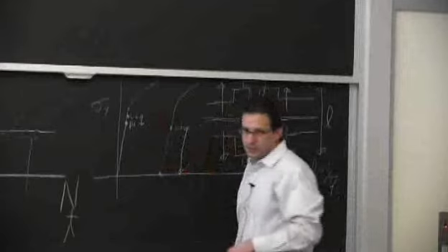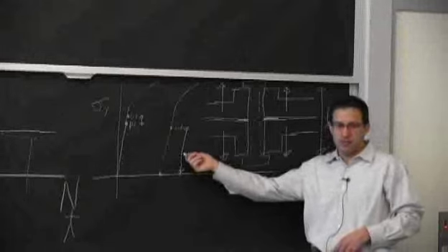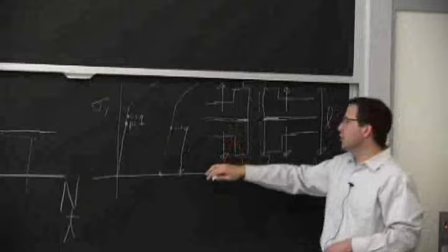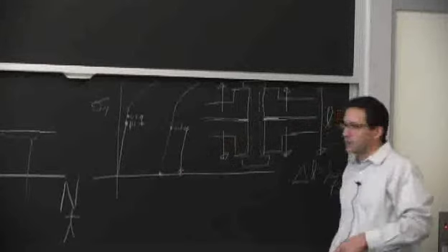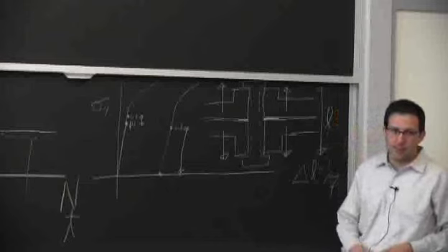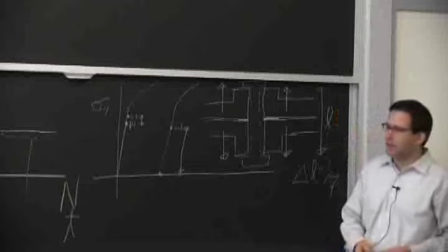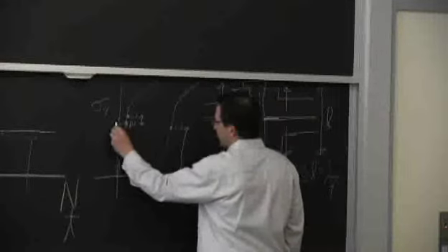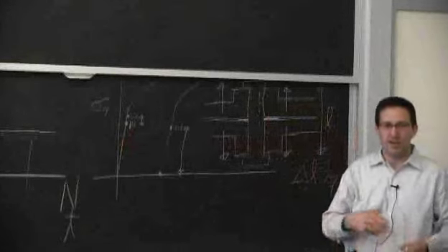it's very different. So you get a whole lot more amplitude of stress from loading and unloading when you don't have the preload. And that's why people have to torque bolts up in critical application. It's not necessarily easy, because when I ask here for that 80% of yield strength, and a guy is there with a wrench, there are different ways to do it.